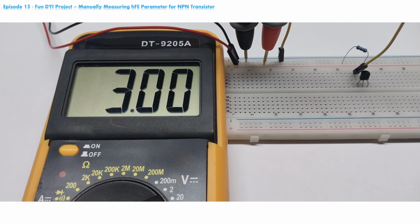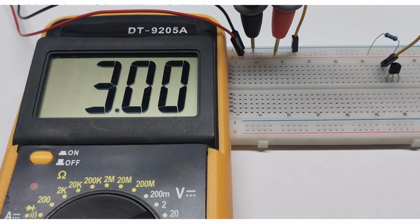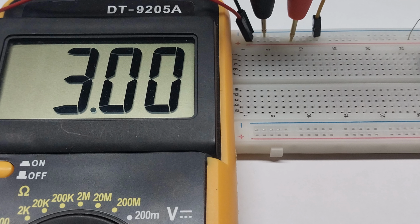Using the multimeter on DC voltage selection, we will insert probes into the breadboard, to measure the voltage that the power source provides. If your probes are of thicker design, and cannot be inserted into breadboard slots, you can measure the voltage of the power source directly. As expected, our power source provides 3 volts of DC power.